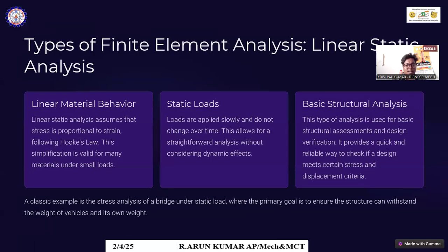So what are the types of FEA analysis, starting with linear static analysis? With linear material behavior, linear static analysis assumes that stress is proportional to strain, following Hooke's law. This simplification is valid for many materials under small loads.